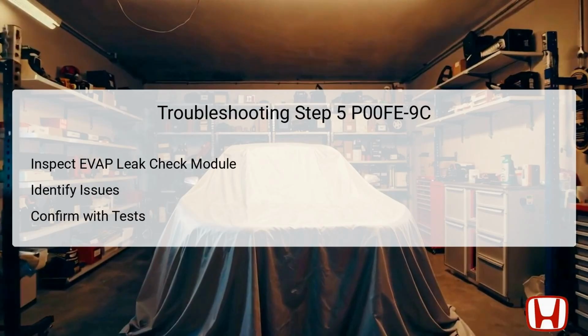In the final troubleshooting step, the focus narrows to the EVAP leak check module itself. If other assessed components have indicated normal conditions, it is reasonable to believe that the EVAP leak check module could be at fault. Conduct functional tests to determine its performance.